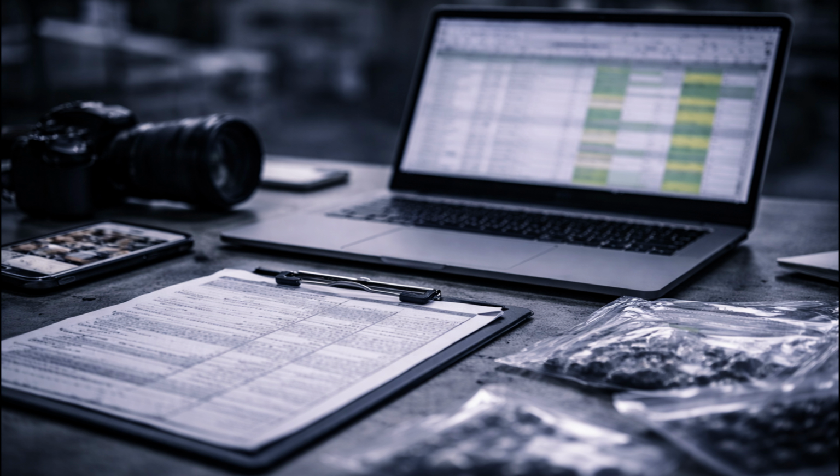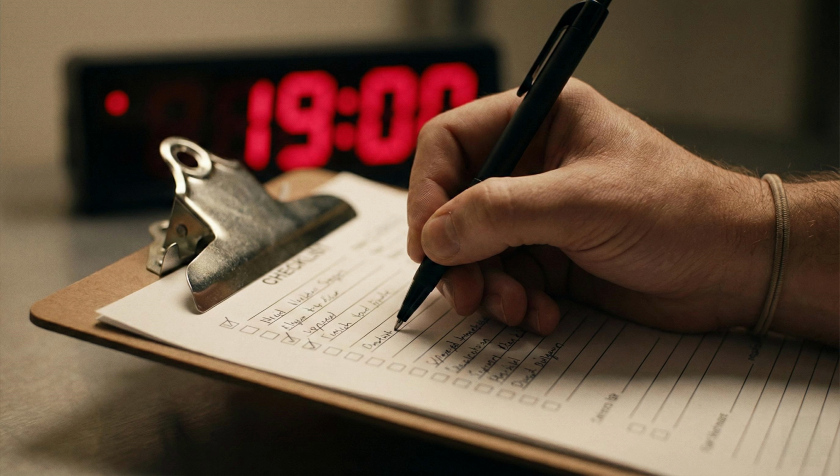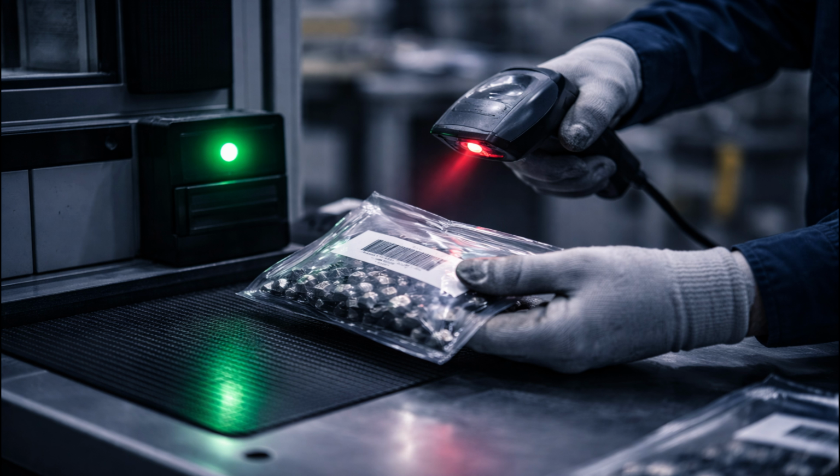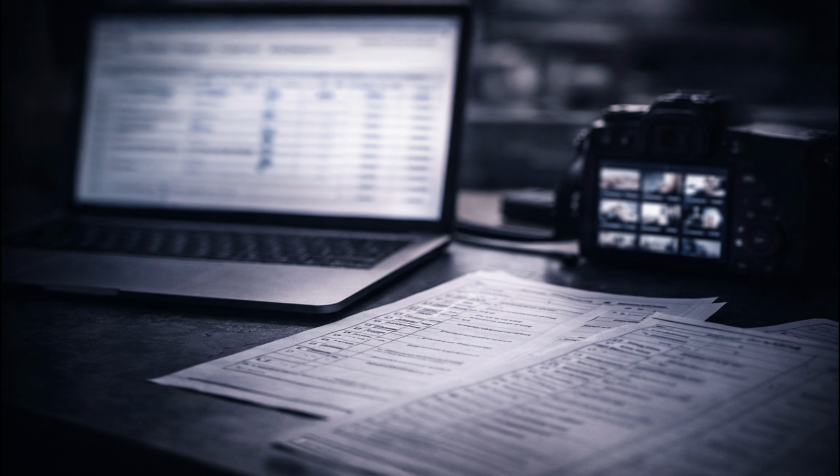What do you do? Review outgoing shipments, quarantine suspect stock, and, if needed, launch 100% sorting. With one crucial difference, we record everything minute by minute. Who did what, when, how many, and how. And then the critical detail, we declare the clean point. From this time, after this lot serial number, every part has been verified and is safe. You must be able to say this backed by proof. Lot lists, inspection records, photos, and data ready to go.